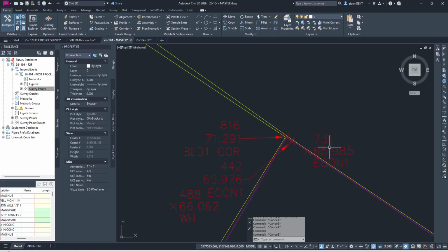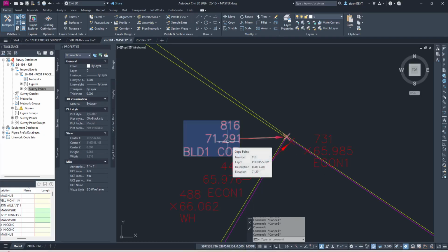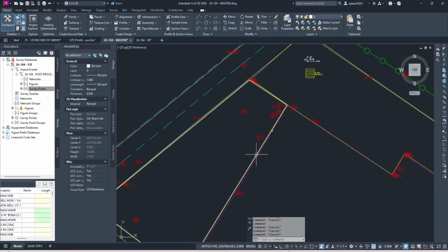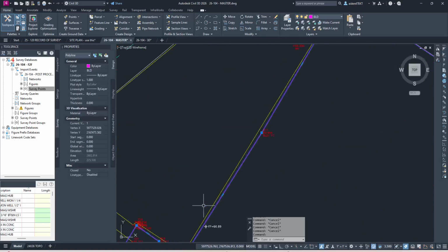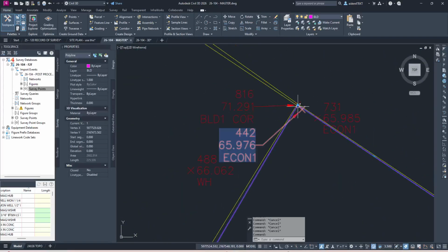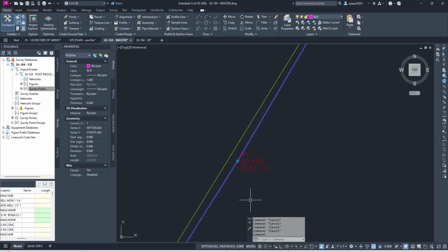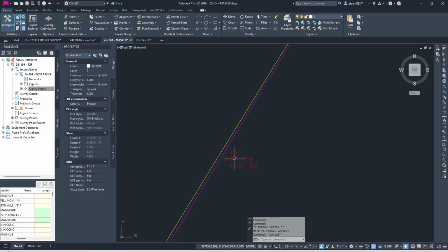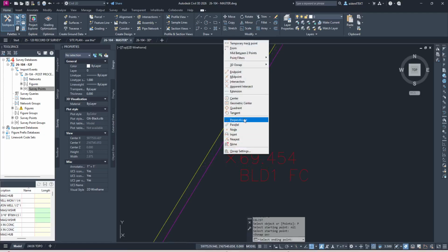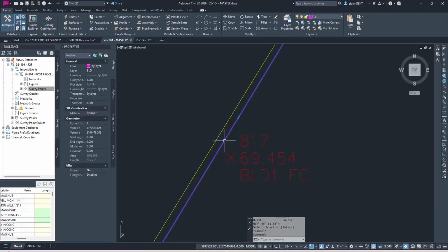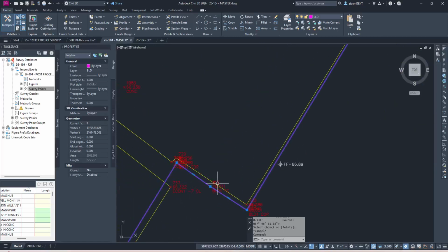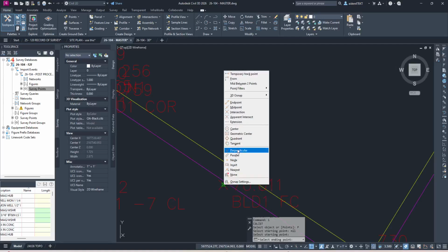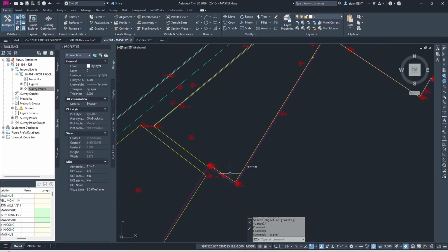65. Okay, that's the same elevation. Obviously the building corner was a DR shot, direct reflectorless shot. But that's a good shot. He's got a shot here in the middle. That's why I tell him to get these. Let's move that. See how far off that is? That's 1300s. Not bad. That's why I tell him to get one of those face shots so we can check to see how off their corners are. Yeah, so that's 300. It's a lot better.